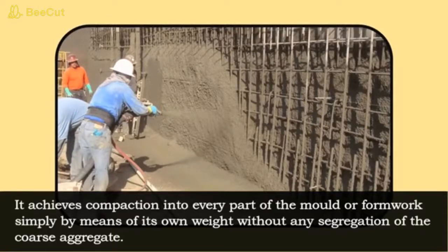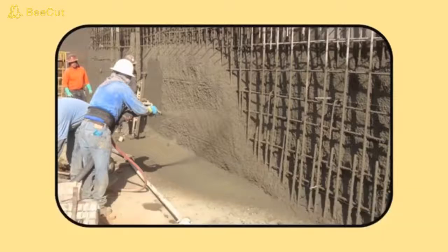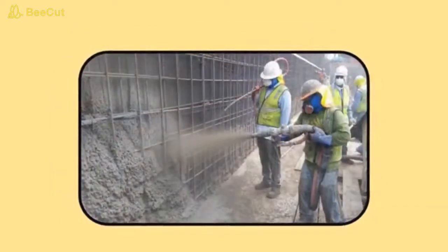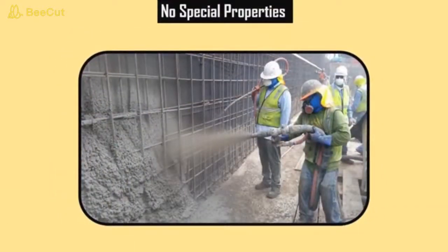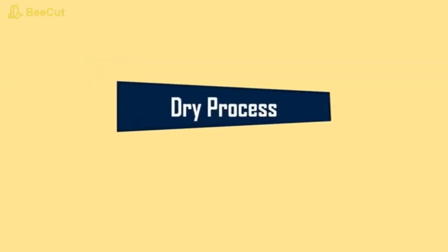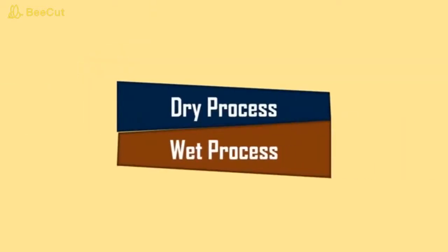fiber materials. In theory, the spraying of concrete onto the surface at high velocity is a perfect method of concrete placement where the placement and compaction are done at the same time. Individual aggregate coated with cement paste are driven into place to form a void free mass of fully compacted concrete.